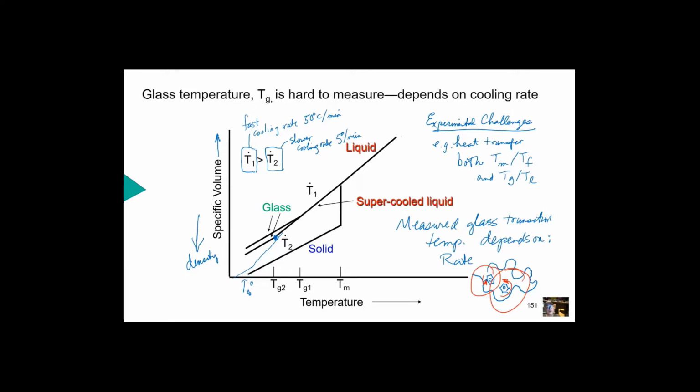Okay, so that's an important difference of glassing compared to freezing. If I talk about freezing, making a crystal of polymer, then all of these elements are either in a crystal, which is the same conformation everywhere, or they're in the amorphous phase, doing their amorphous thing, but there's only those two. But here, if we're talking about glassing this thing, some of these benzene rings may want to stop before others. And there are other kinds of motion here that you can't go into.